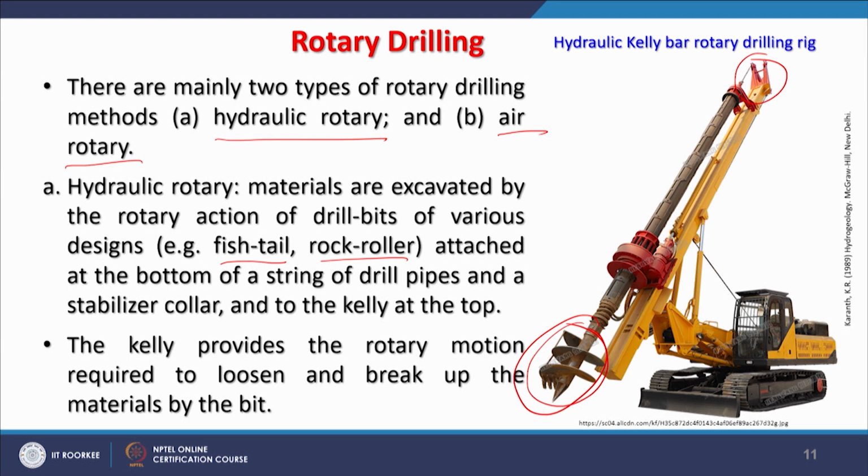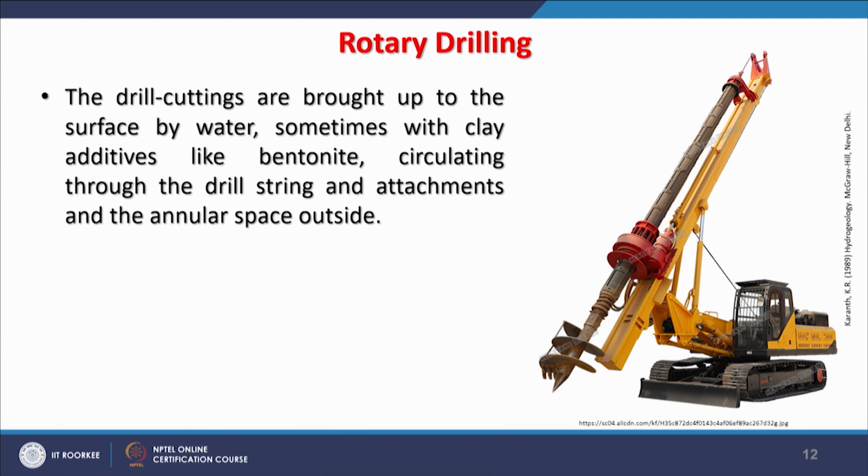Now, the kelly provides the rotatory motion required to loosen and break up the material by the bit. By this action of the kelly, the material in the subsurface is broken, and then further and further you keep doing it till you reach the desired depth. In this drilling, cuttings are brought up to the surface by water, because it is hydraulic drilling, sometimes with a clay additive like bentonite, circulating through the drill string and attachments and the annular space outside.